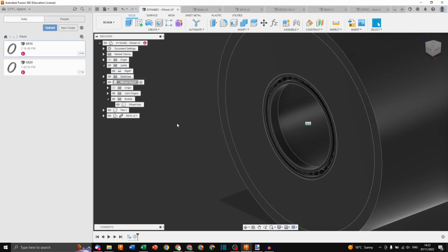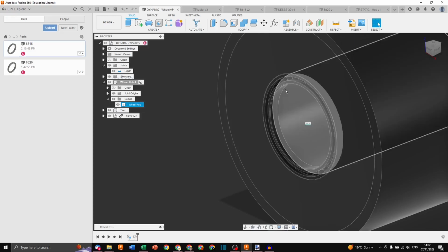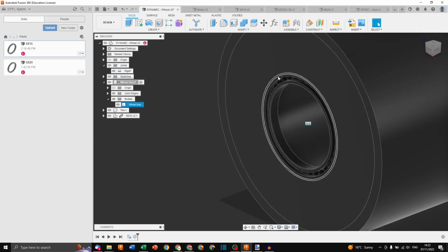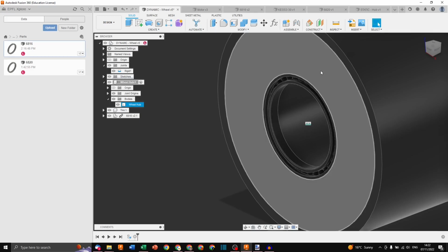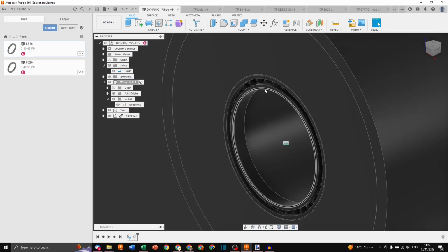So let's now add the second bearing much faster. But before, let's go on a third tangent. You could say, well, why don't you add a rotating joint between the inner race and the outer race? And you'd be right. If I wanted to represent the world perfectly, I would have to add a rotating joint between the inner race and the outer race.